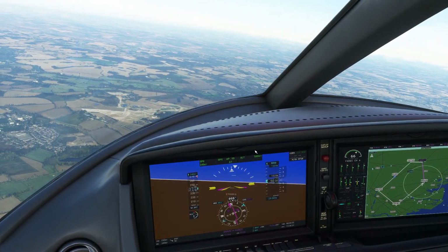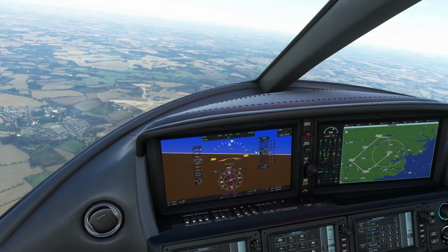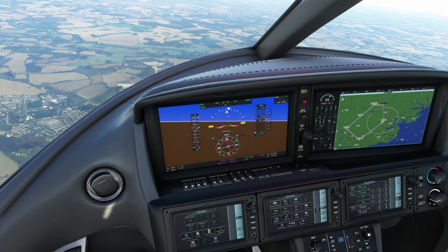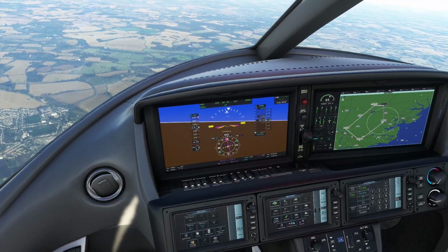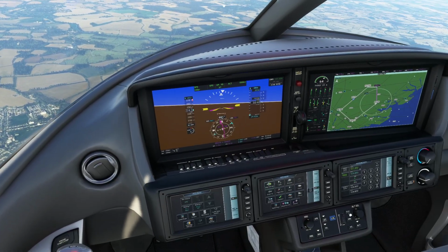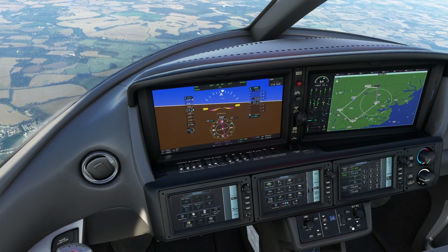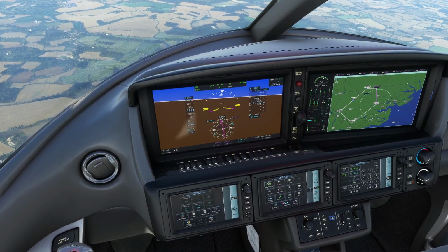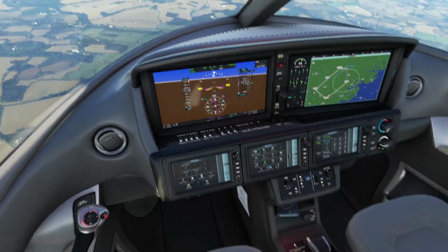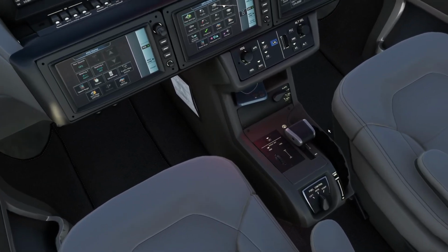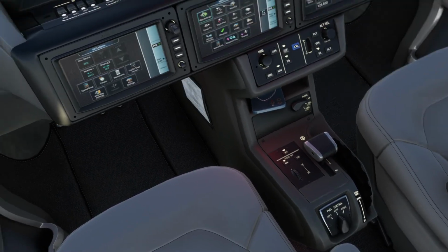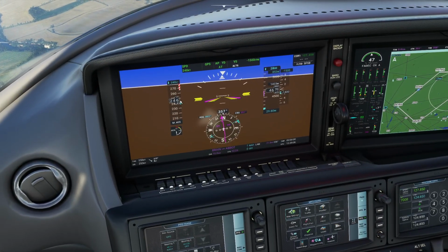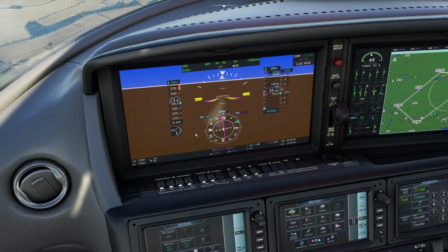Okay, we need to drop down to about 2,800 feet. So let's go and drop our target altitude to 2,800 feet and do a vertical speed to get there. So we'll come down at 1,500 feet a minute. Now watch the throttle. Can you see the throttle pulling back all on its own? That's because we have selected we want to try and stay at 240 knots, and notice it is lagging. It's not managing to do it very easily.